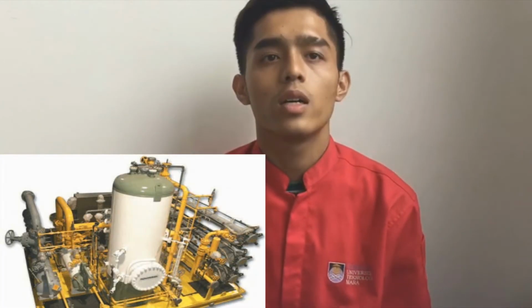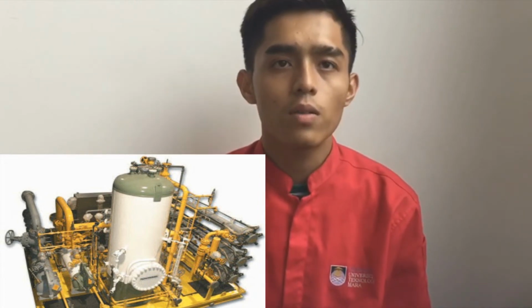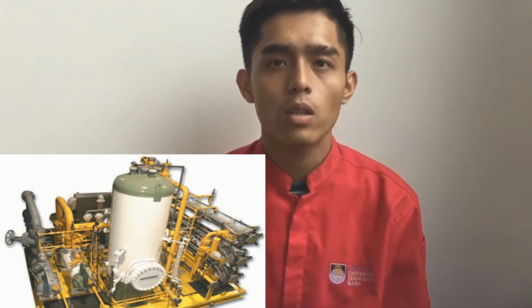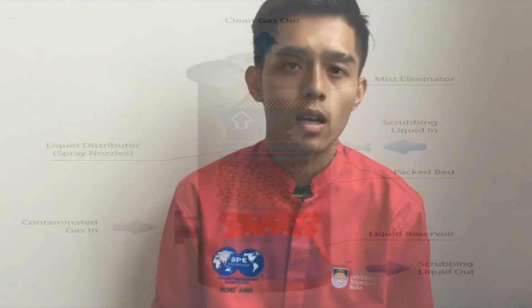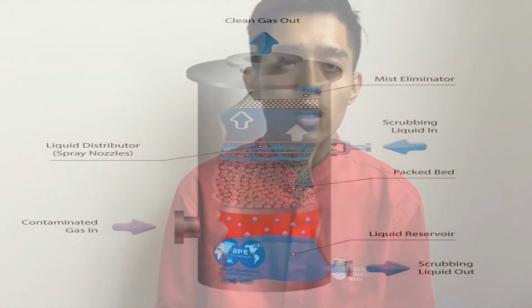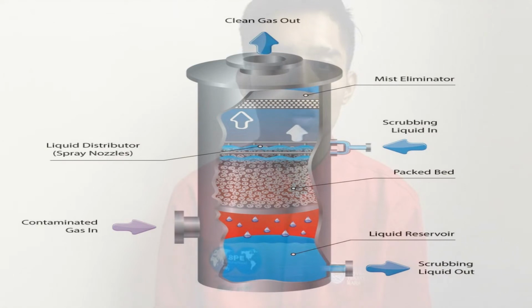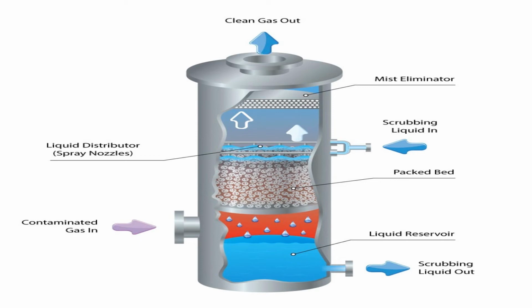Secondly, absorption is applied in production facilities. It is the property of some liquid or solid to soak up water or another fluid. The natural gas dehydration process uses glycol liquids to absorb the water vapor and finally obtain dehydrated gas. Moreover, inlet oil, also called absorption oil, is used to remove heavier oil liquids, such as hydrocarbons, from a wet gas stream to obtain a dry gas.